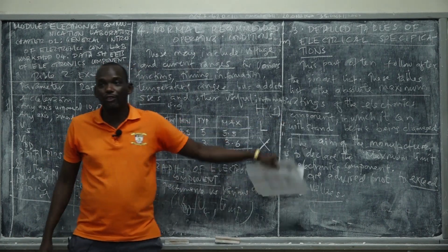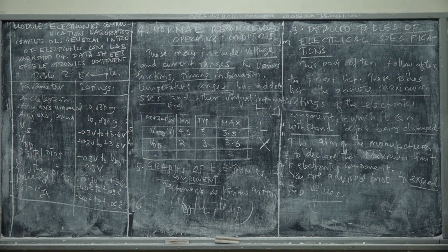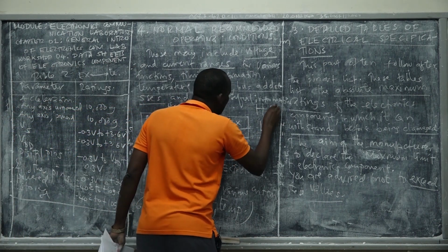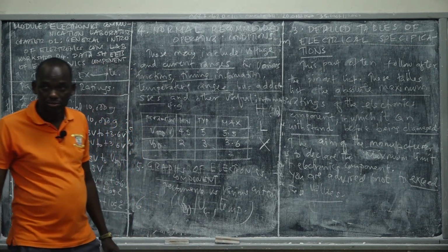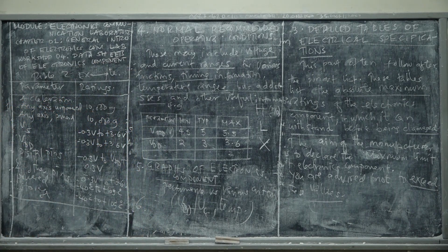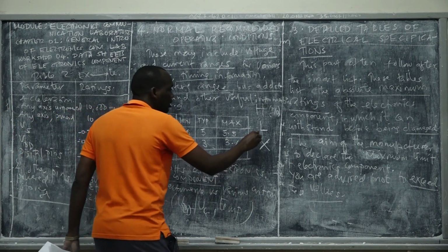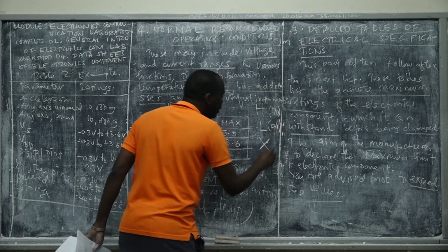Okay, so H stands for high, which means bit 1, right? L stands for low. But sometimes this means bit 1 or bit 0. In fundamentals, we taught you that high represents 1. But I want to tell you that high might be 1 or 0, depending on the situation you are using it in. It's the manufacturer who has to say that H stands for bit 1 or for 0 volt. Are we together? L stands for low, so L represents bit 0 or bit 1.